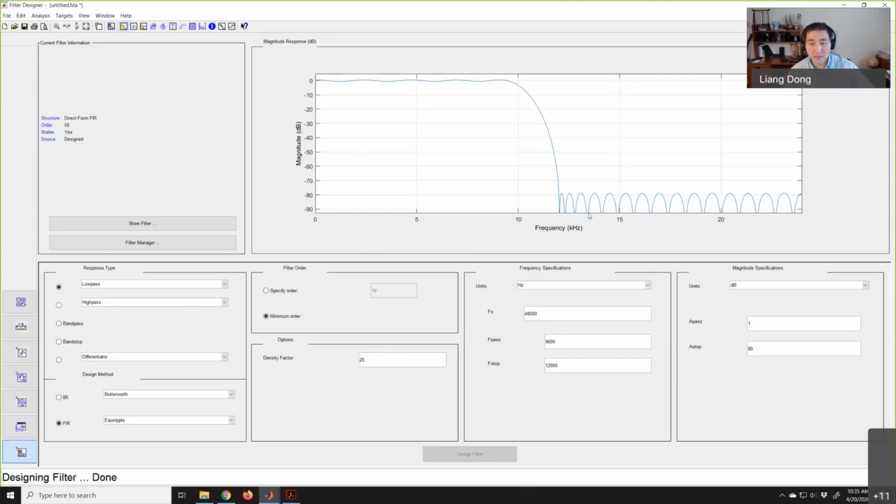Here is the stop band ripple. Stop band ripple that we see here. Actually, this is the delta 2. Delta 2 is 80 dB down. Actually, this is compared with the highest one. So it's 80 dB down. That's a ripple of the stop band. Now, how many coefficients that I have? It's order of 50. I actually have 50 coefficients. So Hn non-zero values are 50 of non-zero values.